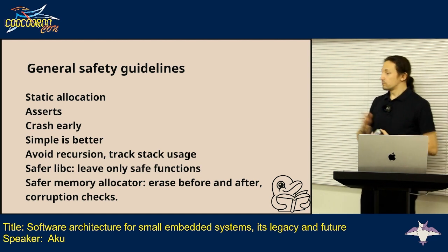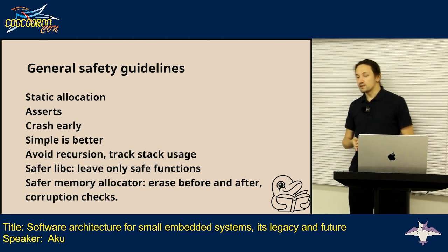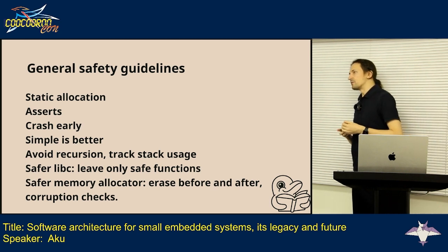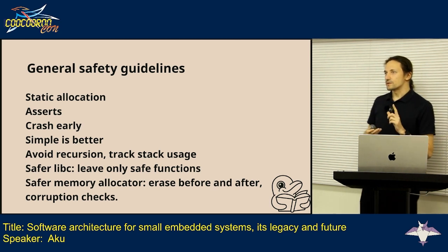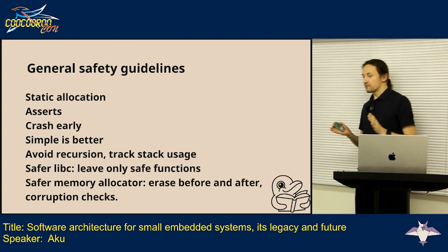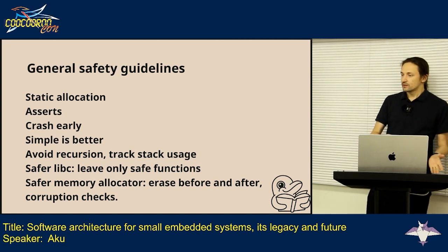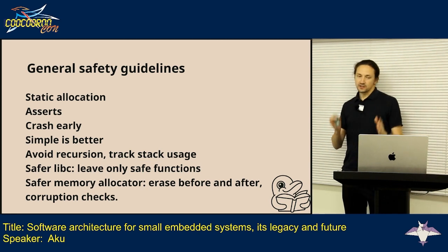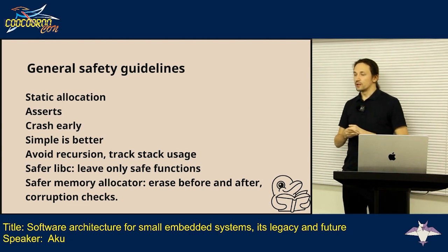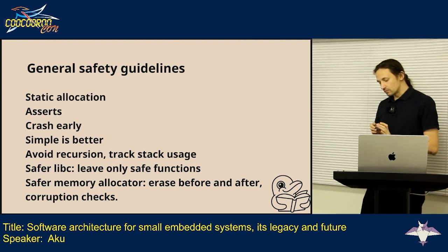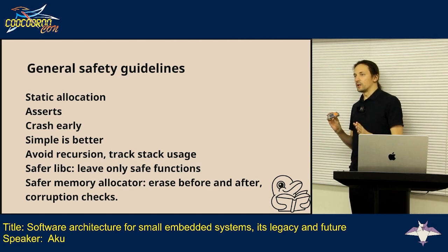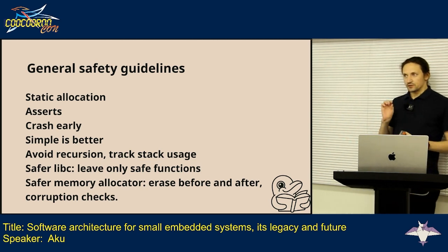So also, one of the things that we do with real-time operating systems, we avoid recursion, not only because that makes everything unpredictable, but also because of the stack. With a real-time operating system or without, we have a fixed amount of RAM, and we definitely don't want to go beyond the stack. Most of the tasks on the Flipper have 1 kilobyte of stack or 2 kilobytes of stack.